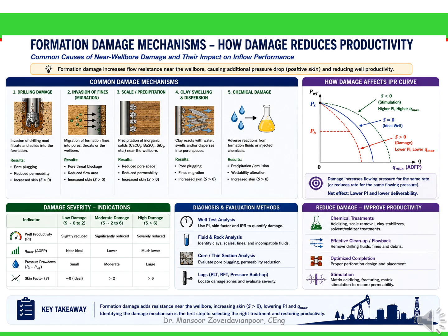This is why engineers never prescribe acidizing simply because a well has a high skin factor or low production. First, they perform pressure transient testing, analyze the buildup data, estimate the skin, review drilling and completion history, and identify the actual damage mechanism.